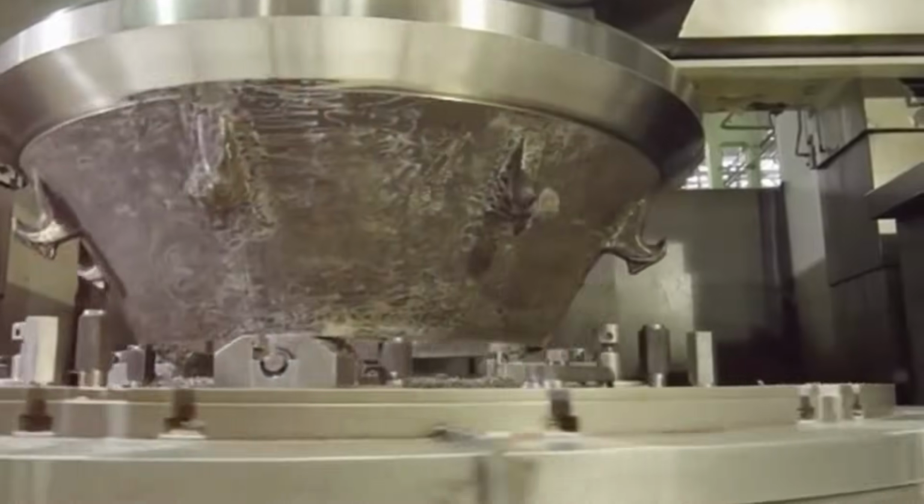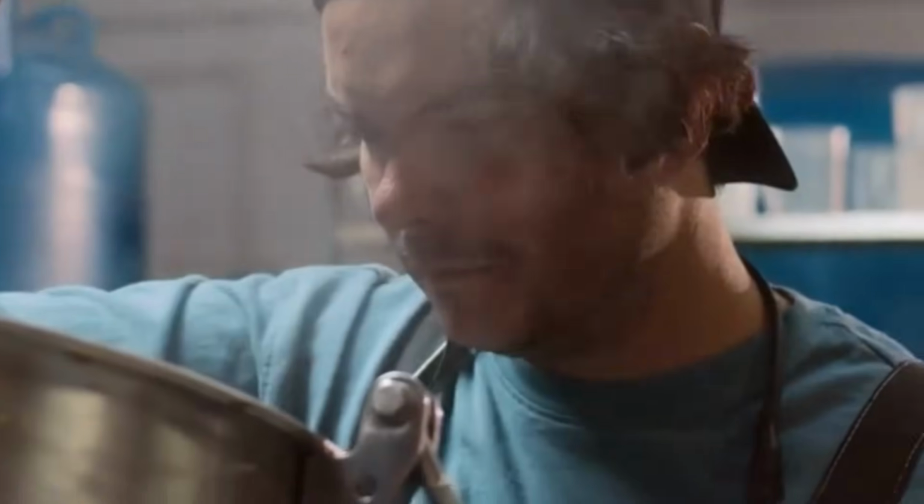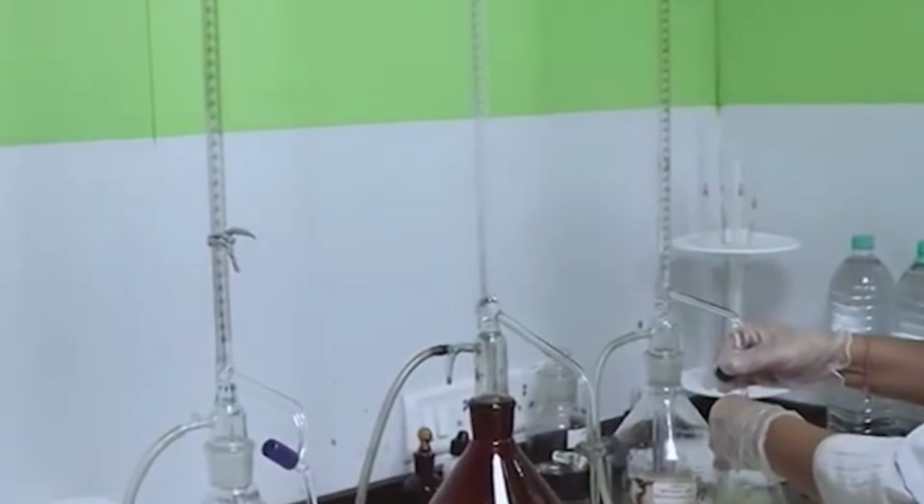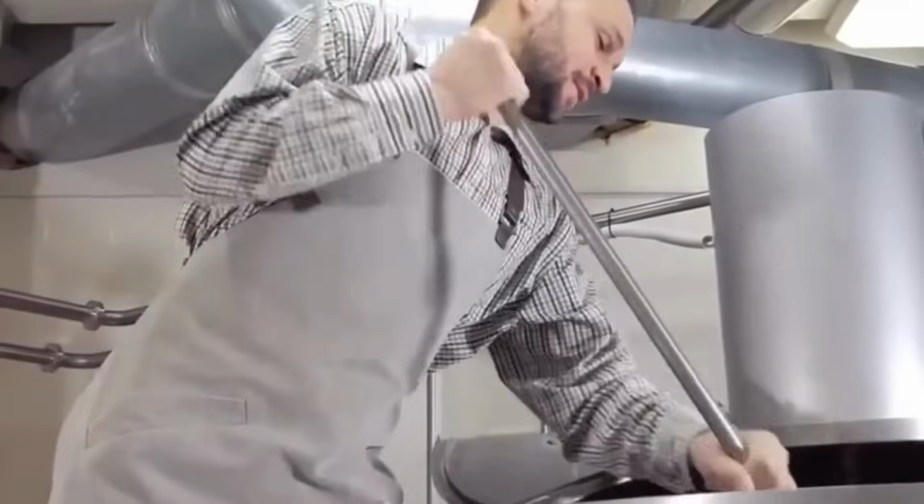From there, it proceeds into a reverse osmosis module, which uses pressure-driven membrane filtration to remove dissolved salts, nitrates, and bacteria. The output is ultra-clean water with consistent properties. Before storage, it is exposed to ultraviolet irradiation and passed through a 0.2 micron sterile filter to eliminate any remaining